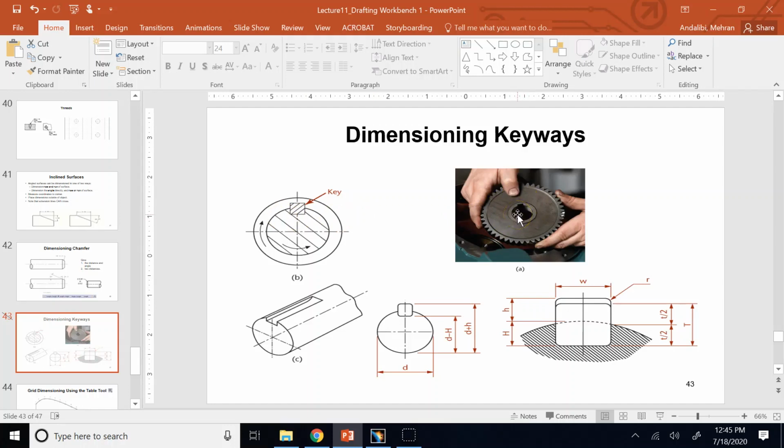It's called a press fit or interference fit, which we'll see in the next lecture. And then you apply some heat to the hole to make it bigger, and you apply low temperature to the shaft to make it shrink a little bit. Then use pressure, and force the shaft into the hole.